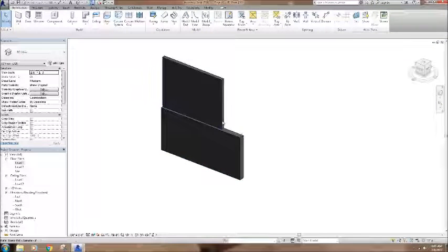So if you're the model manager, maybe that's just your job. You go through and any sort of stacked walls, you're locking those in place so that if anybody wants to move that sort of stuff, they have to go through the warning. It at least puts in a small bit of a fail-safe to get rid of potential problems.